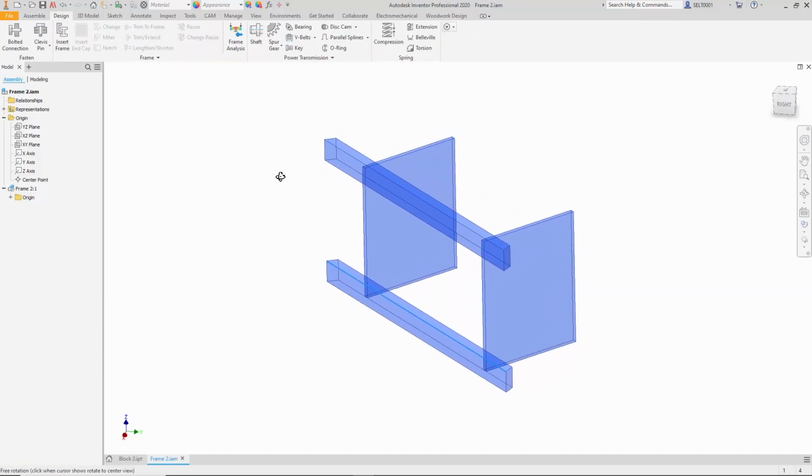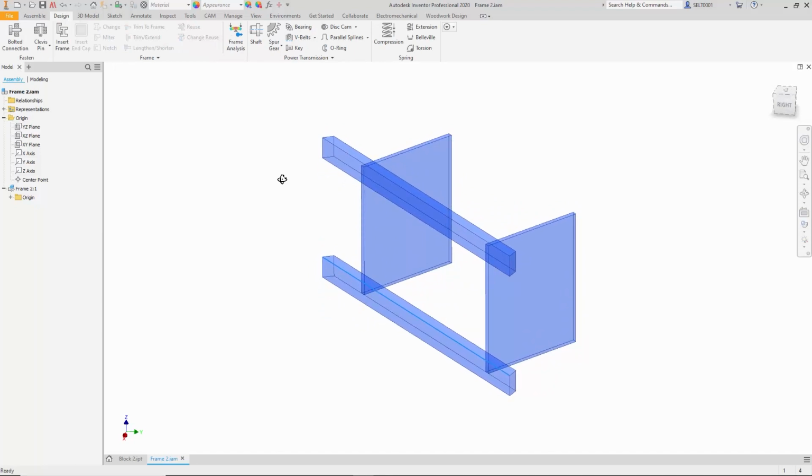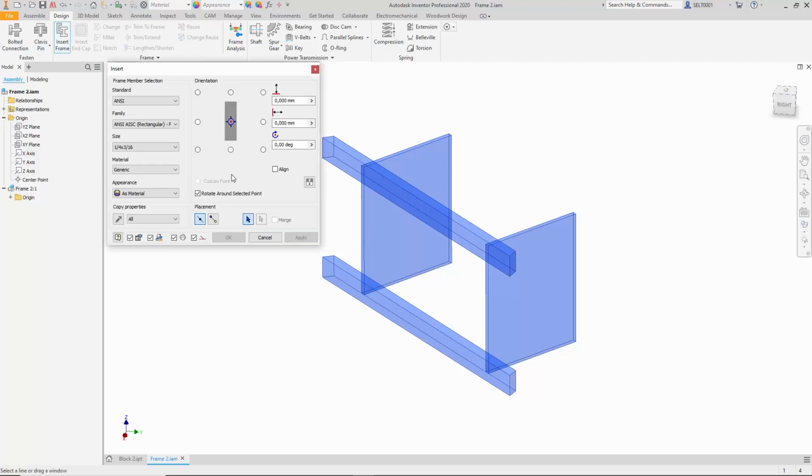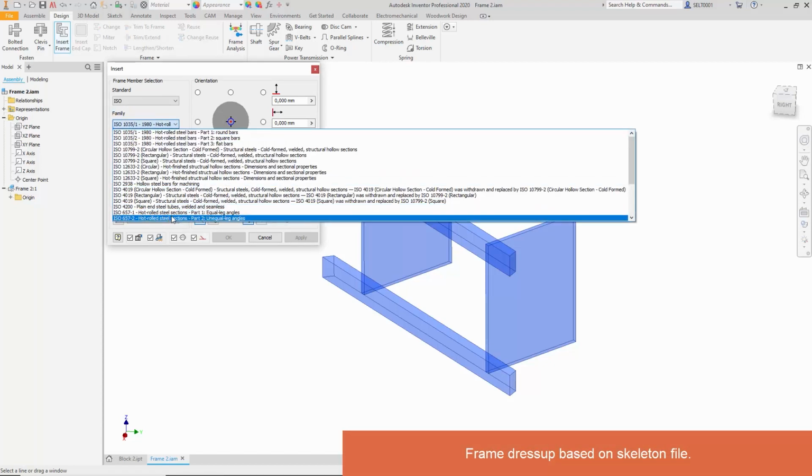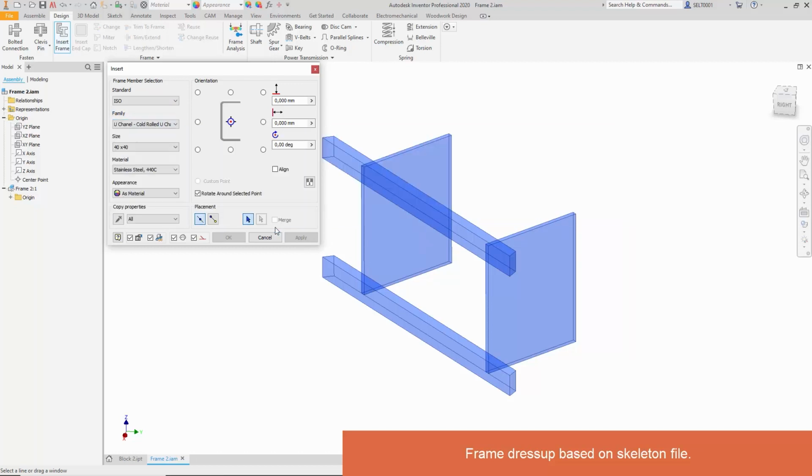Let's take advantage of the Inventor content center and complete the outfit. An ISO profile with a channel is required. Specify which profile is required, 150 profile size. We turn the profile 180 degrees and align it with the point. We perform the same action with another profile. The position is selected based on the baseline. This way we get the position of the next profile.